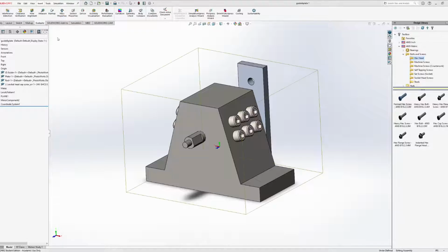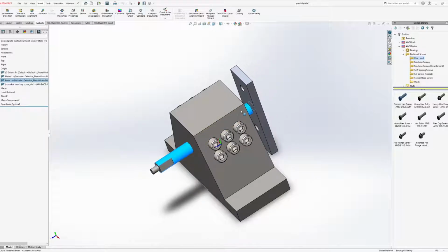So the one thing that I would say to that is, and maybe you already did this, but we do have to be able to show or specify that new coordinate system. So in the mass properties menu, it will say report coordinate values relative to blank, or it will just default, which is in reference to the global coordinate system. So you want to click your global coordinate system 1 or whichever it is. You can recalculate that, or hit recalculate, if certain things are being adjusted while you're working with it.